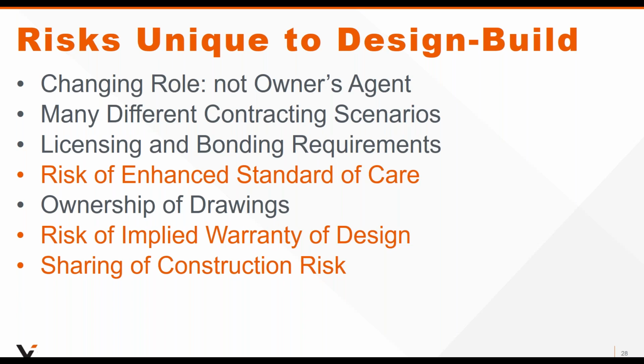One thing that we'll talk about in a little more detail is that we often see a risk of an enhanced standard of care when it comes to design build, and you need to be cognizant of that. The ownership of drawings could be an issue that needs to be addressed, especially, oftentimes what you have is a teaming agreement that says, okay, let's team up. We will work towards preparing a proposal. But you want to make sure that if the contractor is successful, for example, that they don't choose to ditch you and move on to a lower price design firm after you've done the work.